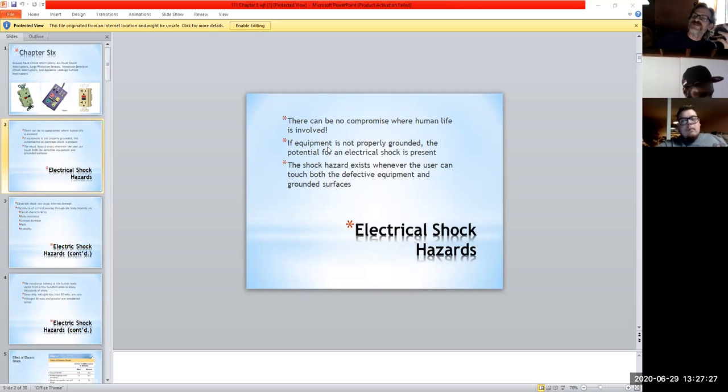I always like to use the example of extension cords. You don't know your extension cord's compromised. Let's say somebody in the house ran over one of the extension cords with a vacuum cleaner and it got chewed up but looked okay. So you just put it back on the ground and let it go, right? But in reality, it ripped up pretty good. If you get a break in the insulation, you can have little arc ripples happen, but it's not a big enough current for anything to trip on. So here you've got this shock potential just sitting there, right?